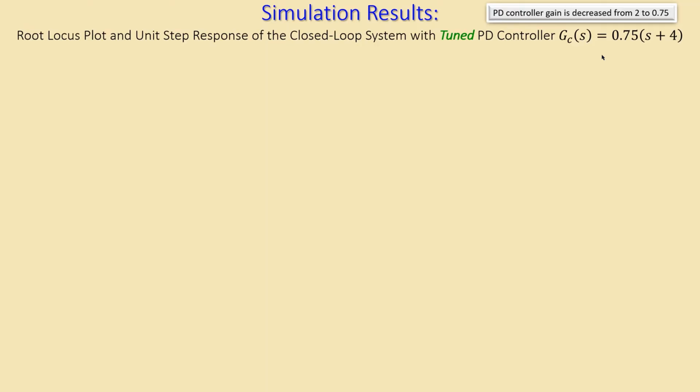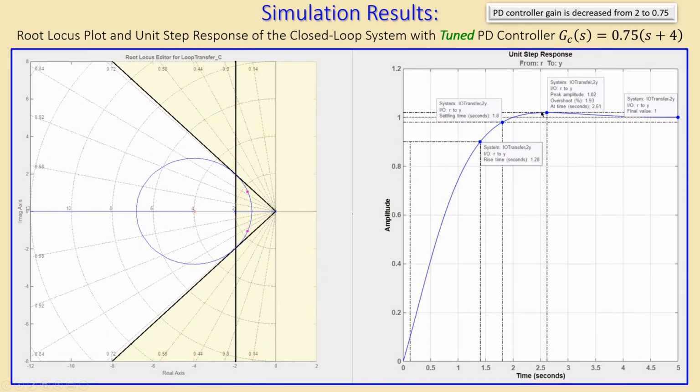So by placing the gain of the P controller, actually of the total controller, a little bit lower, maybe I can also lower the overshoot. That's actually the motivation to go for lowering the controller gain and not increasing the controller gain. So this is the result, and I can see that the dominant closed loop poles, assumed dominant, are now here.